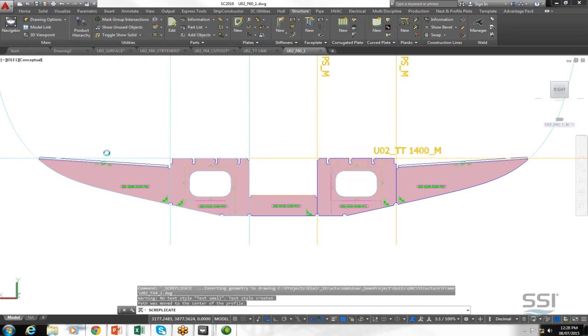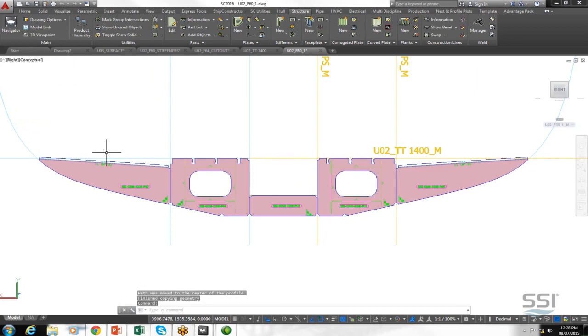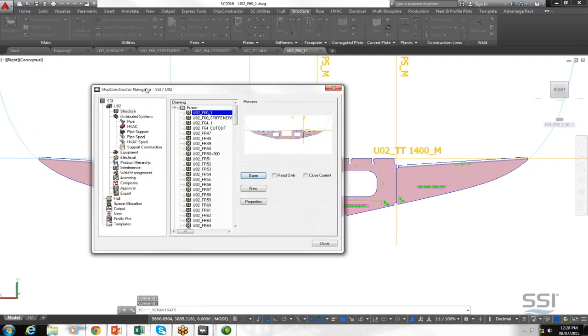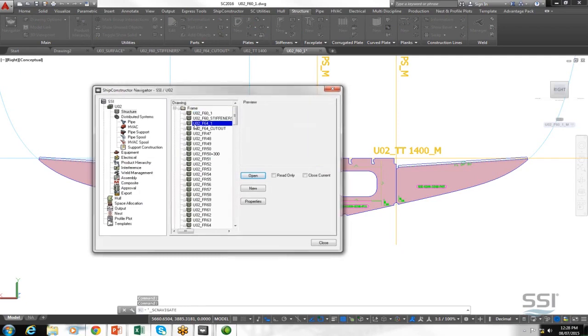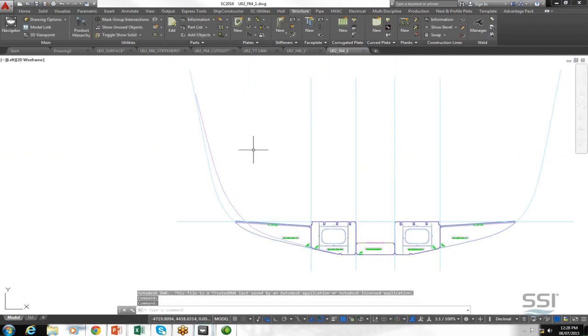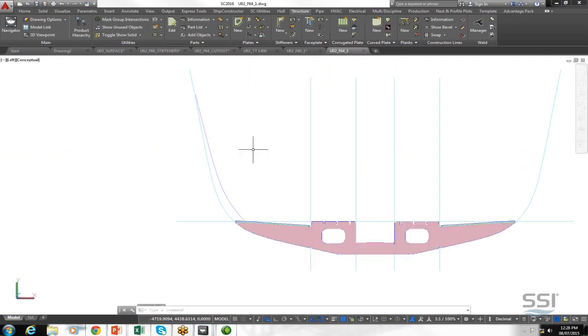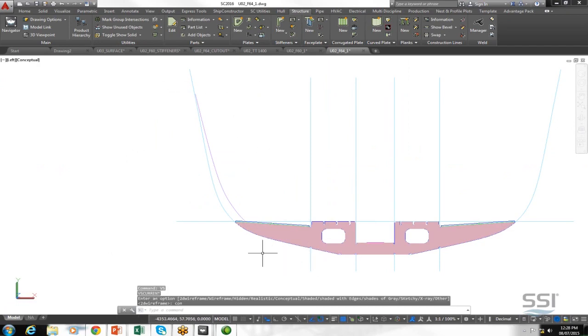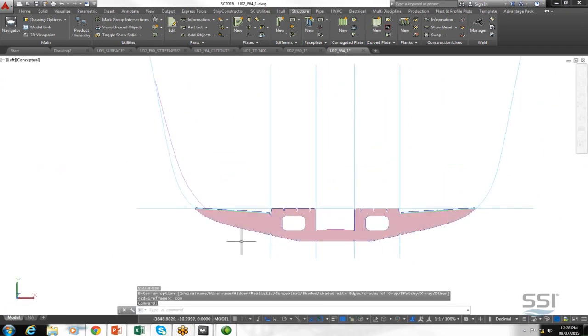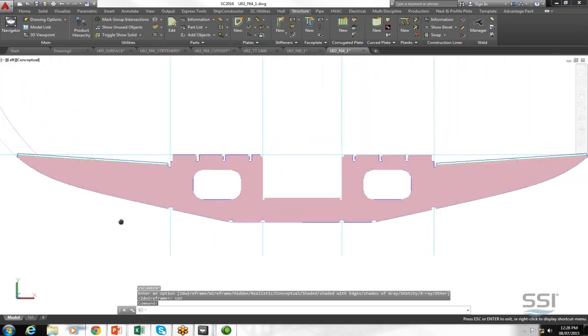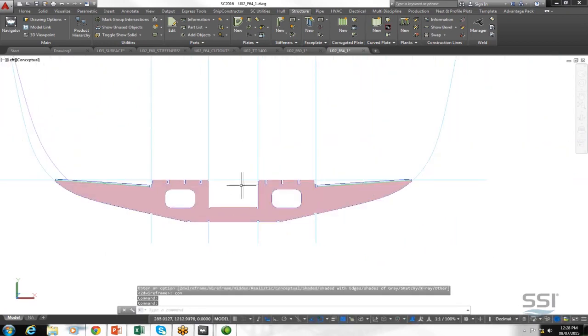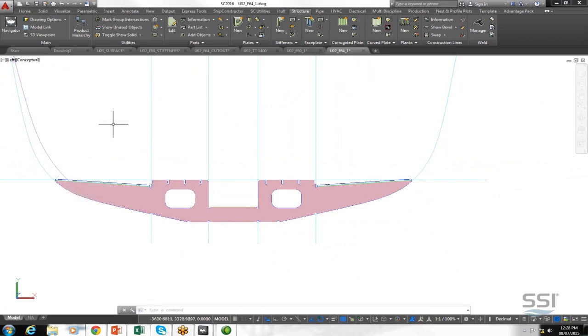You can see briefly there was some calculation going on regarding the stiffener. It's just checking to see if the stiffeners that we have cutouts for still apply in the new location. Otherwise, we've got our geometry copied over, so we can go and open up our frame 64 again. Switch over to a 3D visual style. So we can see now our frame 60 geometry in our frame 64 drawing, and we can see our new hull outline.